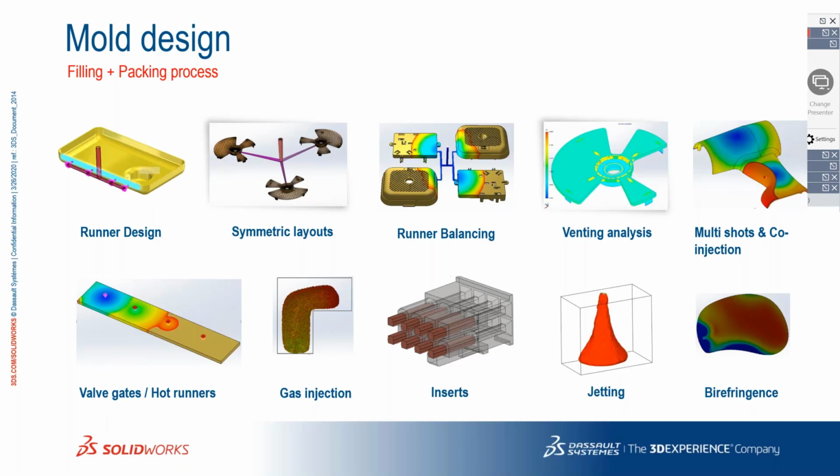And gas assisted injection molding and insert molding are very common in electrical and electronic appliances, where I have the metal insert which has different characteristics altogether. Mechanical properties, chemical properties, everything changes, and the temperature also differs. So to maintain the temperature uniformly throughout, we have to have the options to fill with the temperature of the metal. We have to maintain the temperature of the metal so that it should not distort, and also of the plastics material which is going to fill along with the inserts.